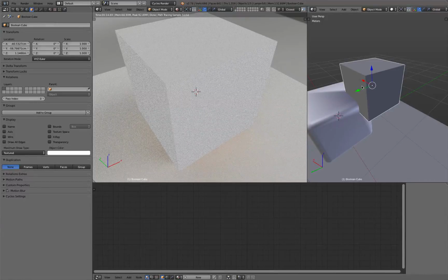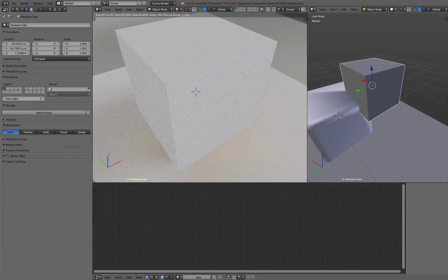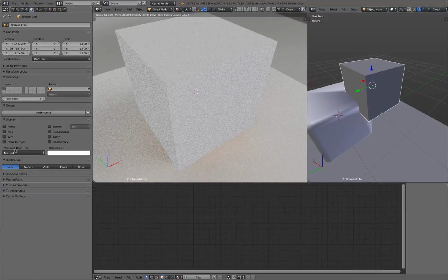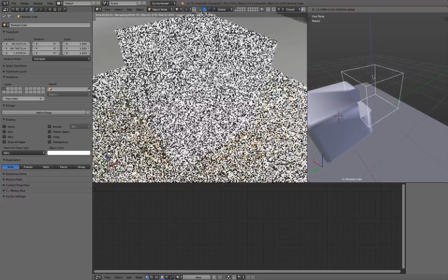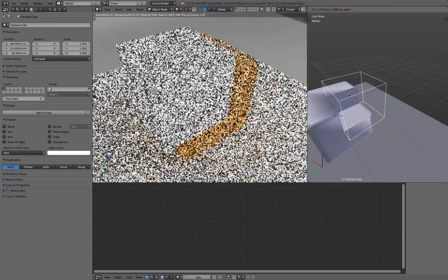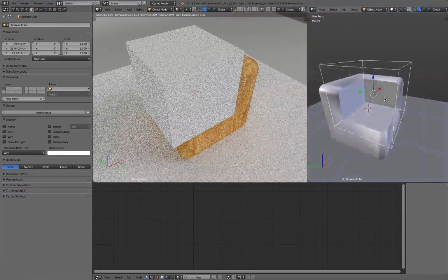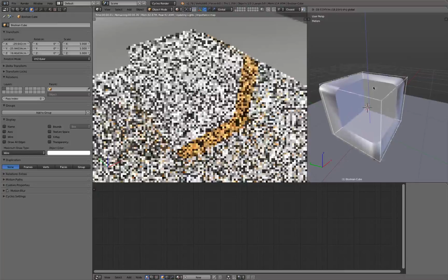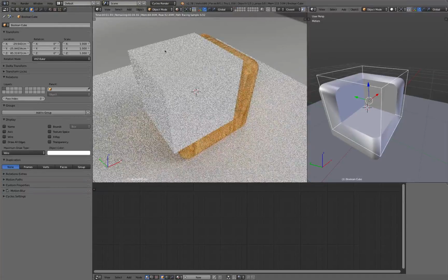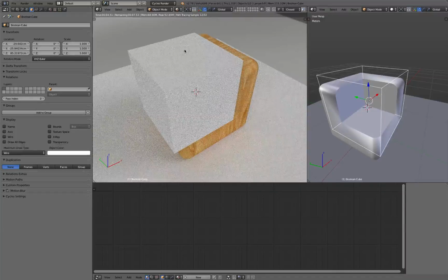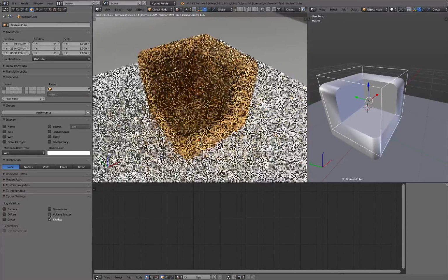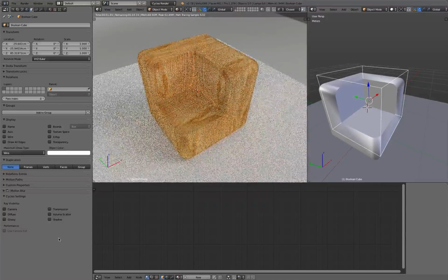And in my 3D view here, I would like only to see the wireframe. So I could go to display, maximum draw type, instead of textured, say wired. So now you can see how I can move this around in real time and see how this cube actually cuts the other cube. But in render time, I still see that cube. So if we go down here to cycles settings, there's also ray visibility, and we can turn all the stuff simply off. Okay.